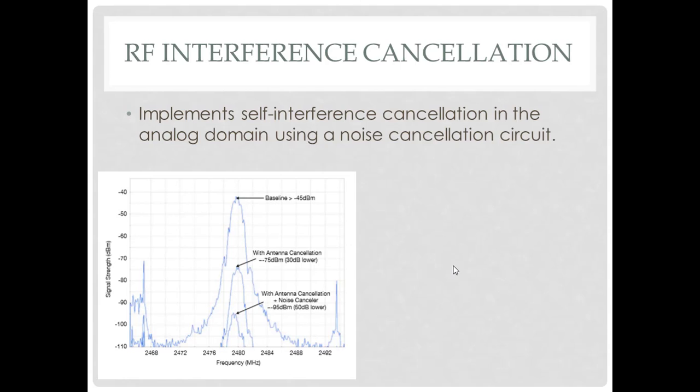For example, the QHX220 noise canceller chip takes the known self-interference and received signals as inputs and outputs the received signal with self-interference subtracted out. The chip allows changing the amplitude and phase of the interference reference signal to match the interference in the received signal. And a radio frequency splitter is used to give the transmit signal to the cancellation circuit as the interference reference.